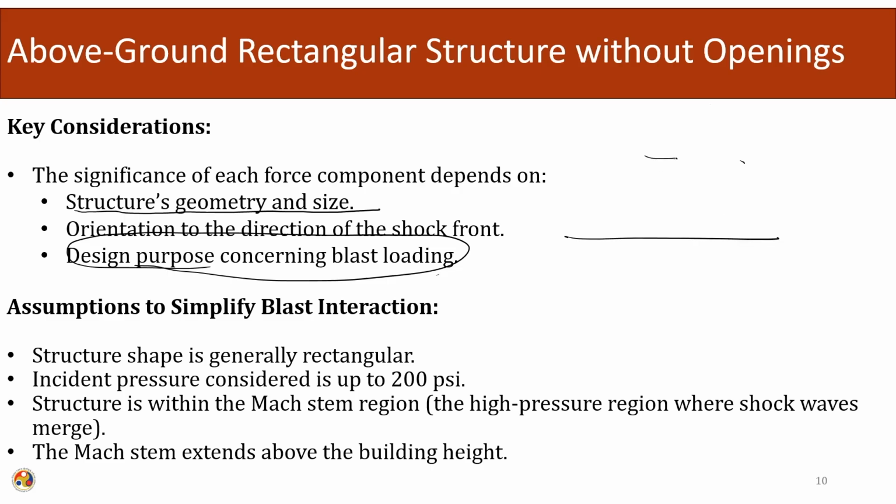For the deflections, we normally like our structure to behave in an elastic fashion. So normally we are used to having only one performance level. But in the blast loading case, there can be different performance levels, and depending upon the use of the structure, a performance level specific to this structure can be fixed. This structure can be designed so that cracking does not occur.